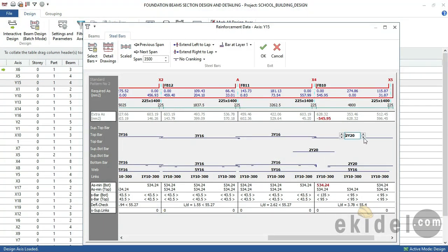Okay, so right now again, I'll remove this one entirely, and then come here again, reduce the bar diameter and increase the number to 3. Now our 3 is still failing, so I'll make it 4. Okay, 3, don't worry, 3 is okay, but at the bottom here, I need to lap it to stop this failure here. So I'll come here right now, lap it here, reduce the diameter of the bar, and then increase the number.